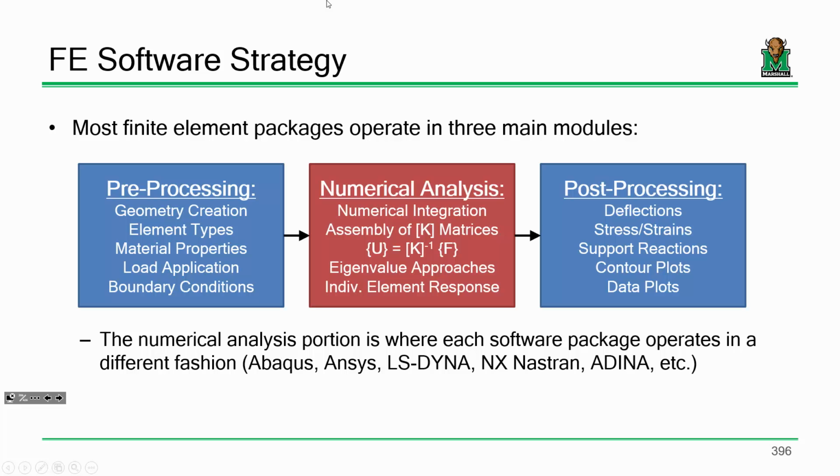Okay? So what is the numerical analysis? That's the engine that actually runs the program or runs the model. So it numerically integrates all the elements. It assembles the K-matrix. It solves for the displacements or eigenvalue approaches or what have you. And then it breaks it up and does your individual element response, the stuff we've been doing all semester.